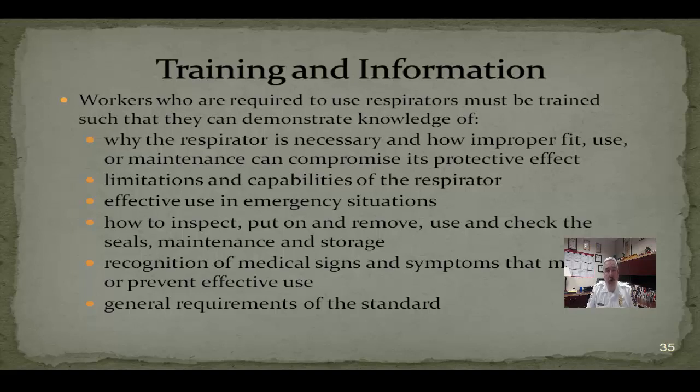We'll record what size face piece that you wear. We'll make sure that we're looking at any kind of changes or alterations to your face, that we're providing you with a properly sealing mask. We've got to be constantly looking at the mask itself and make sure that it's still in good working order and it still provides you with a good seal.